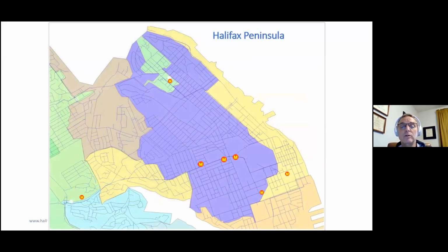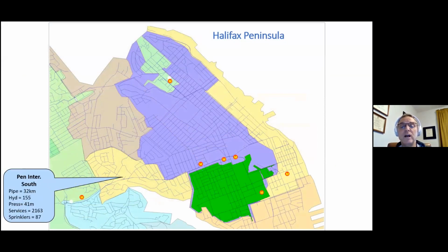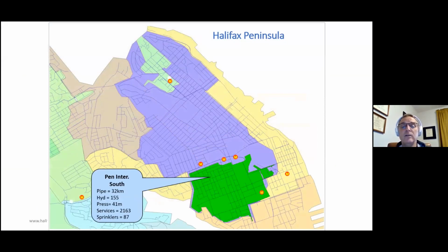So here we go. What we did, we basically isolated a section and we closed a lot of valves that were already open and flowing freely. And we installed 3 meters across that boundary because we wanted to make sure we're measuring flow going into this sector and flow going out. Okay, so we always know what's happening within the zone.